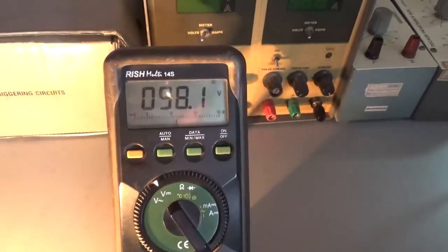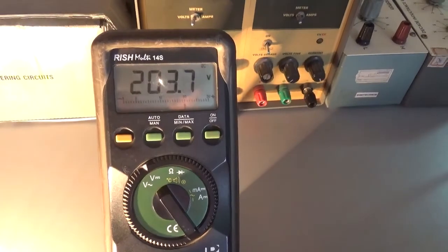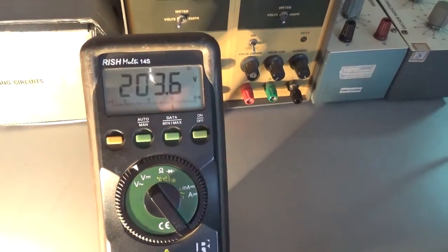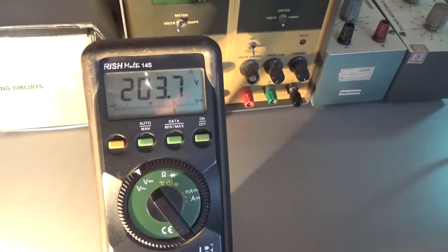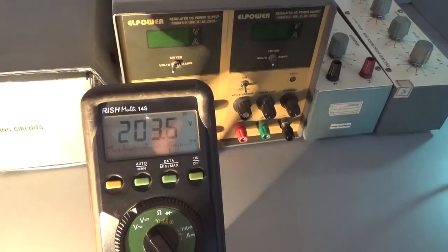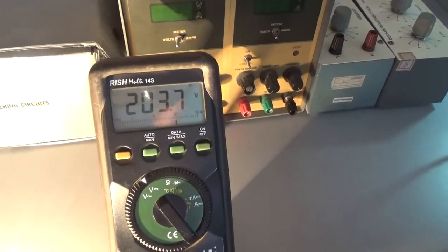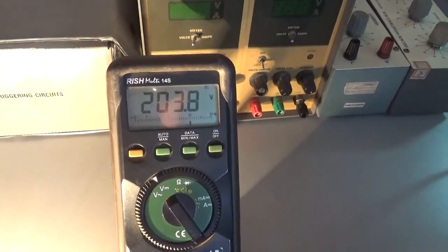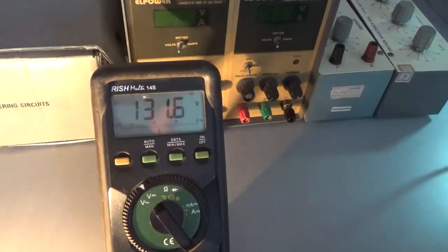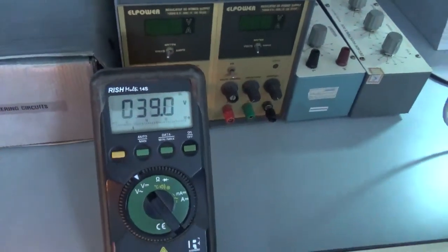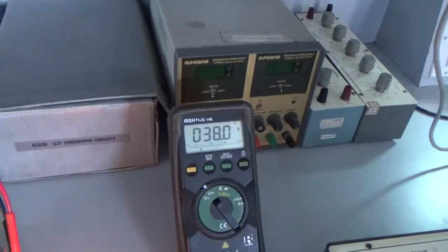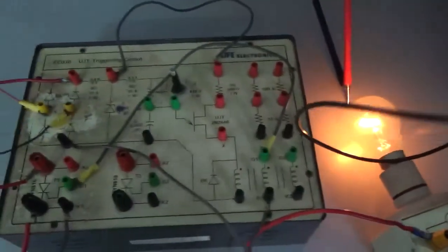Now as you vary alpha, the voltage across the load changes. You can observe here, since it is a full wave rectifier, when alpha is equal to 18 degrees, the output voltage is 203.6. In the previous case, it was 101 something. Since we are rectifying both half cycles, in this case the output voltage is more. As you increase the value of alpha, the output voltage keeps on decreasing. You have to plot the graph between VDC and alpha, and then plot the waveforms across the SCR and load. This is all about the conduction of the full wave rectifier using UJT relaxation oscillator.